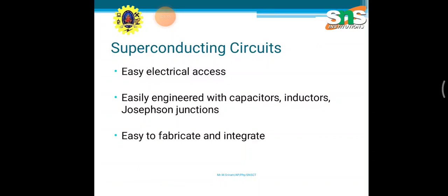The traditional superconducting materials used for SQUIDs are pure niobium or lead alloy with 10% gold or indium, as pure lead is unstable when its temperature changes rapidly. To maintain superconductivity, the entire device needs to operate within a few degrees of absolute zero, so it is cooled with liquid helium.